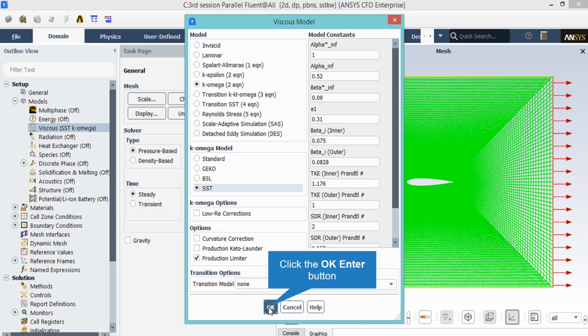In the K epsilon model, the velocity profile in the boundary layer is assumed to have a logarithmic shape. However, in the assumption of the K omega model, it is stated that we should take the mesh cells as small as possible so that the assumption of linear velocity profile in each of these small cells can become valid. But now, using the SST K omega model, we can benefit from the advantages of both models, meaning that we can solve our fluid flow problem faster since we do not need small mesh cells in our whole domain, and that we can obtain more exact results near our wall boundaries.